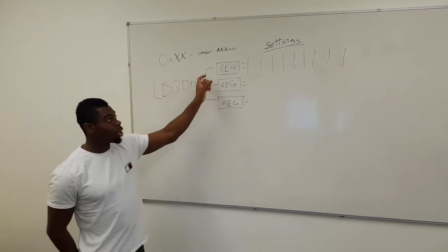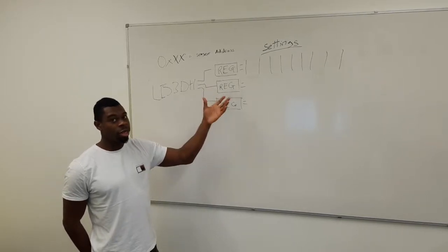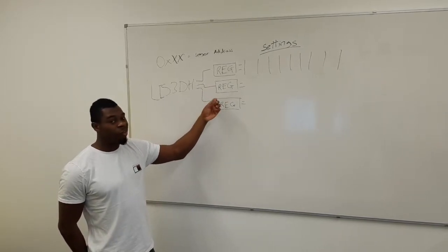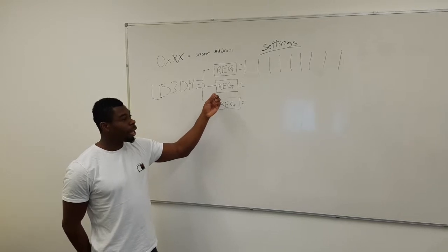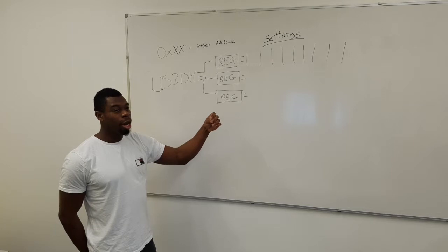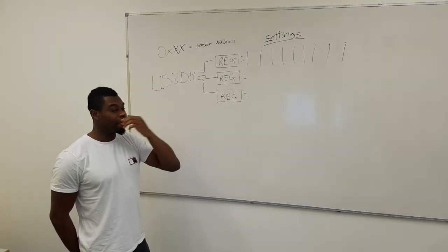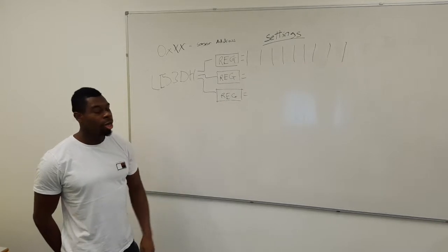And within those particular registers, there are further settings that you can do. So there'll be an 8-bit address, which you can use the hexadecimal value to essentially instantiate more settings within that. For instance, you want it to be a high or low frequency. Would you like it to be a particular power setting, and so on.